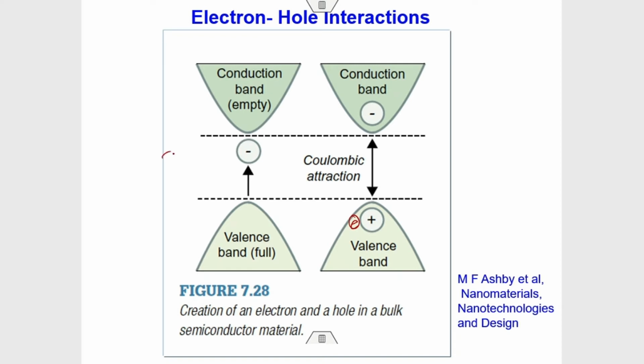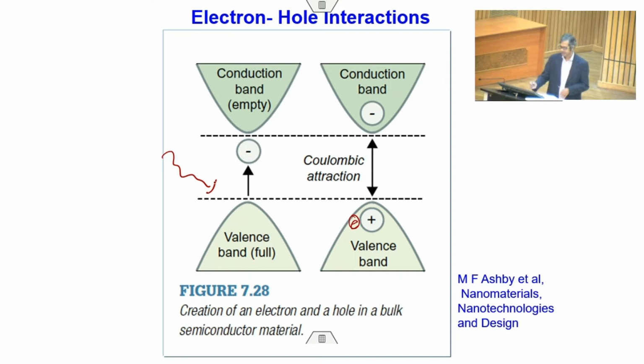Okay, I have a photon energy coming into the picture. If this photon has sufficient energy to drive the electron from the valence to the conduction band, then only the photon will be absorbed, right? Otherwise, why would the electron absorb a photon if we cannot have a transition from valence to the conduction band? But in bulk semiconductors, what has been observed, very simply at low temperature, is that this optical absorption can happen below the energy gap.